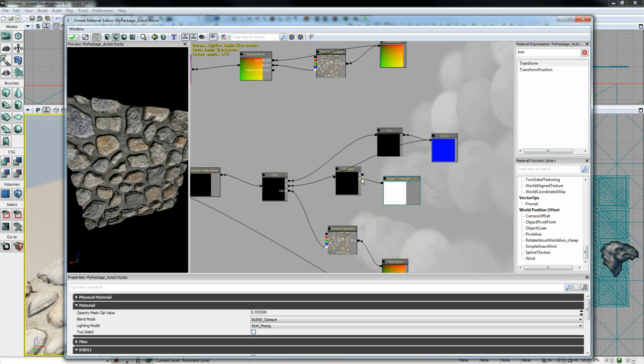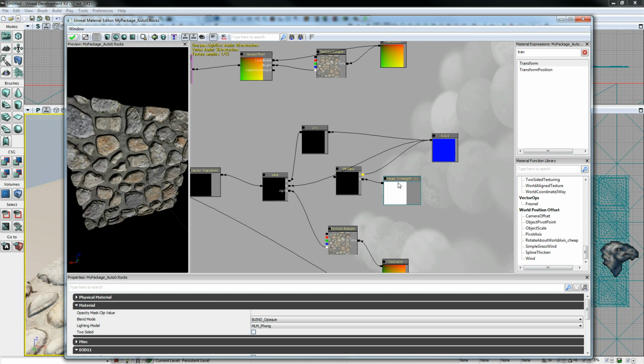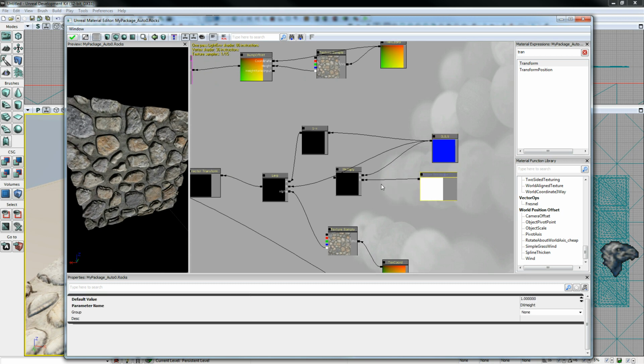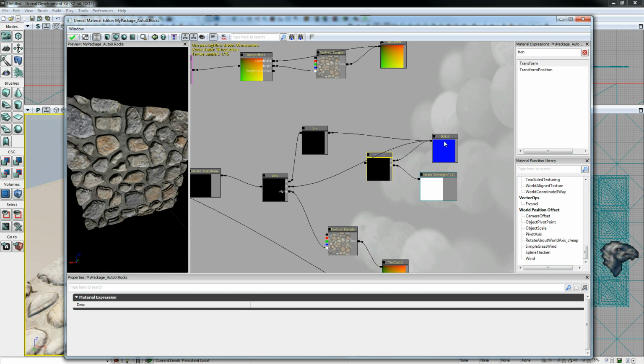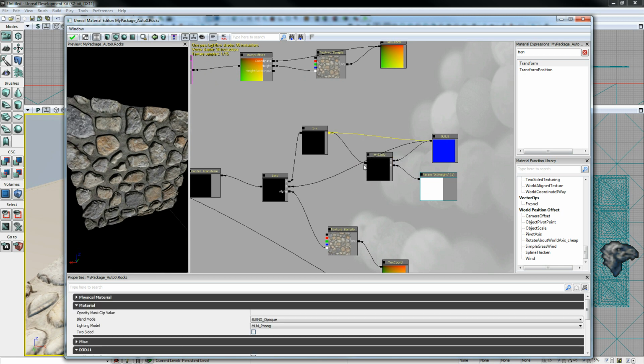So then literally you plug both things. You plug this there, and this becomes the new value for that, basically. What this means is you're just setting it up so that this can be multiplied by this, which dynamically changes it when used in the material constant.